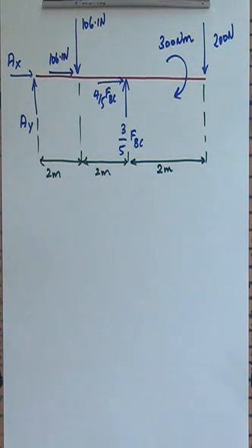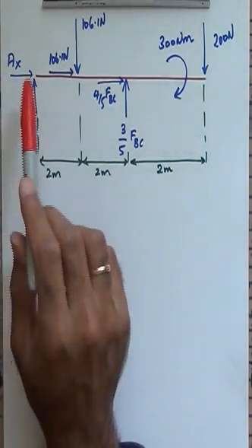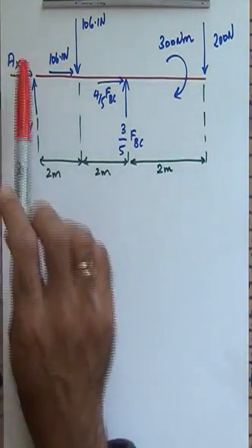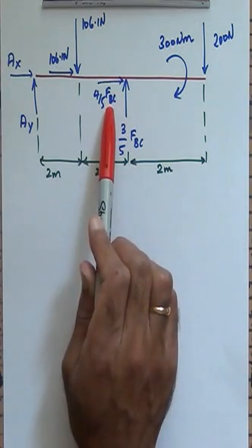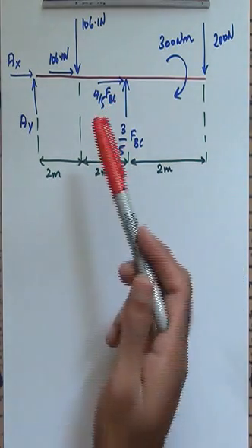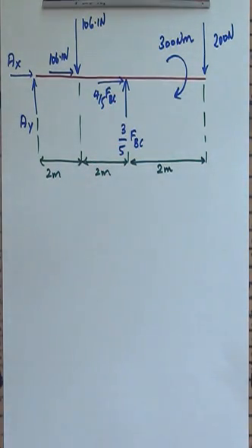Alright, so now we are ready to perform the force balance on the bar ABD. And to perform the force balance, let us start by summing moments about a particular point. You see, my rationale for summing moments is this. If I start summing forces in the x direction, I have AX as an unknown, 4/5 FBC is also an unknown, I have two unknowns, only one equation. I can't solve for any of them.